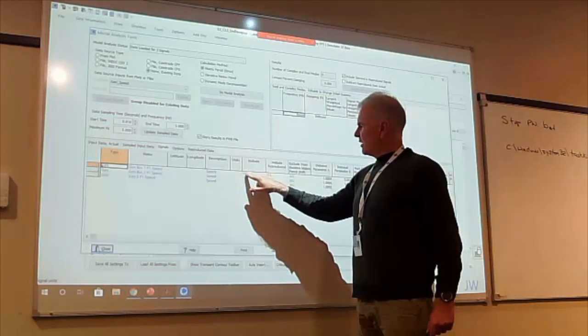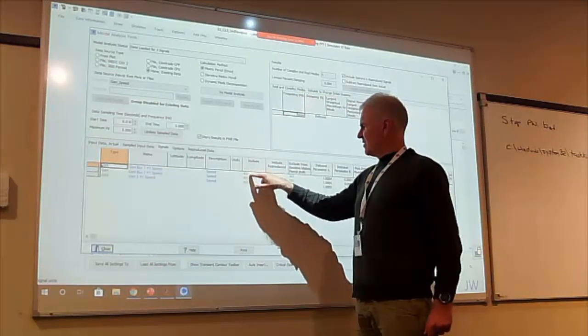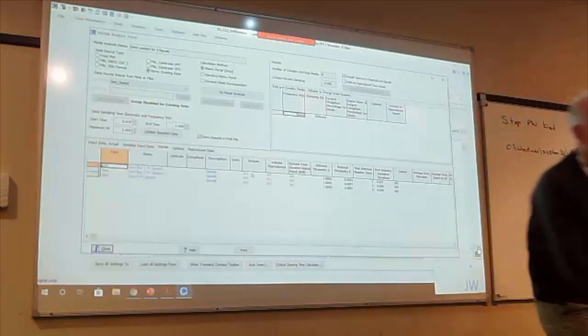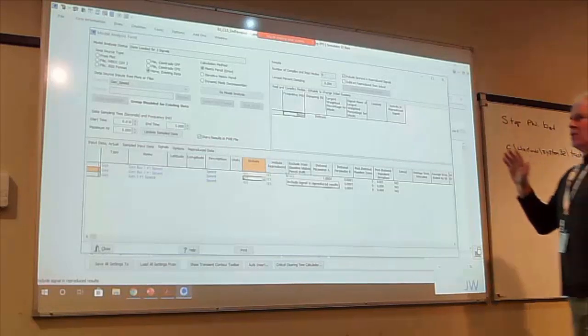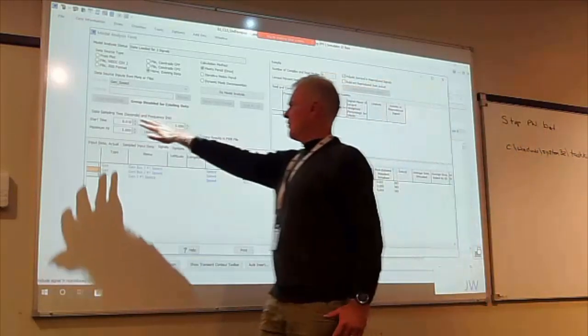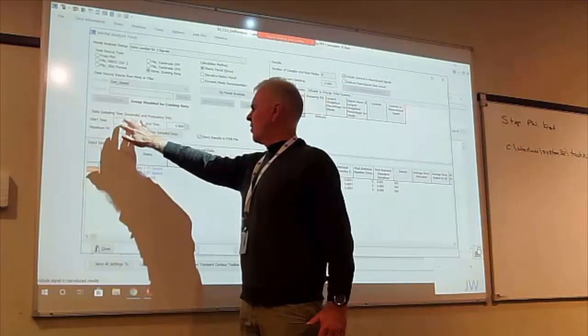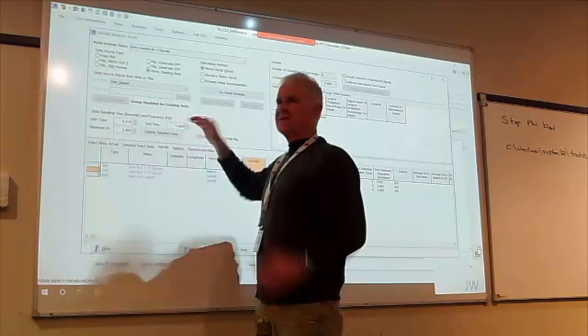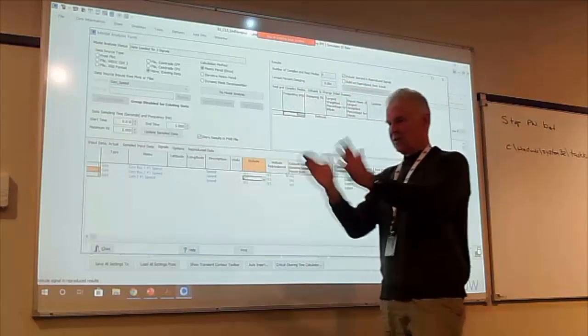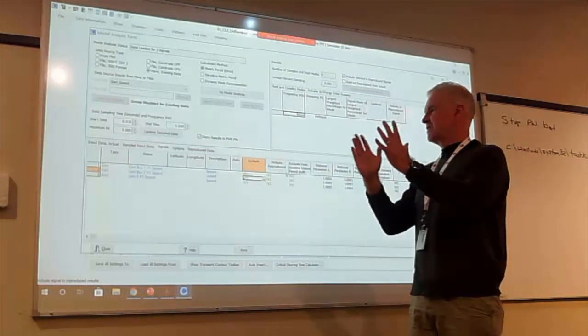If we include it in modal analysis, this is set to yes. Toggle the first two to no, and that's going to say just analyze signal 3. When you analyze a signal, you have to tell the software when I want to start analyzing it and when I want to stop analyzing it. Time in seconds. So this is a signal, and we're going to look at that signal and sample it.